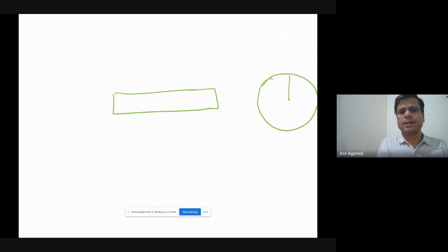The cross section that is outside of the plane of this screen is pulling this cross section shown here in this direction, and the cross section that is outside is being pulled in the opposite direction. So there is this kind of a shear stress acting, and this shear stress is maximum right next to the edge, and it's almost zero at the centroid.